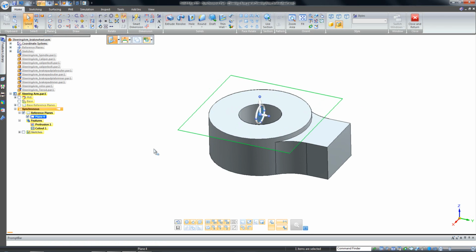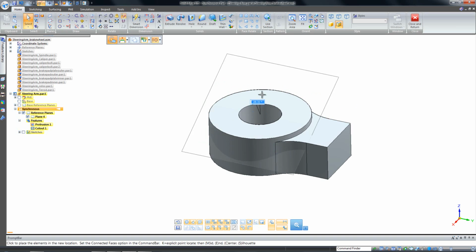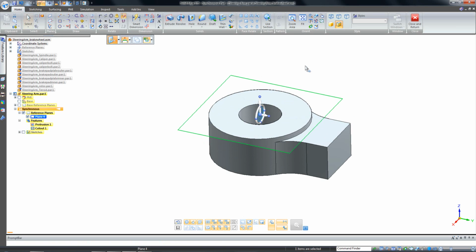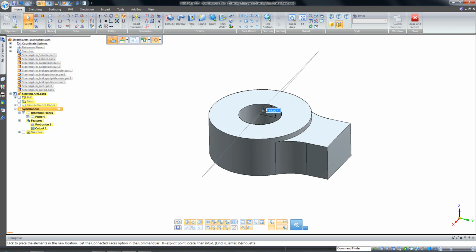work than is necessary. With Solid Edge, when you're working in synchronous, I can easily touch the face of the part and it creates a coincident plane, but notice how the steering wheel automatically pops up. So basically, if I wanted to create an angle, I can go ahead and do that, or if I wanted to change the angle or the way that the angle is being modified, I can also come through here very easily and change the orientation of the steering wheel and maybe create an angled plane in this orientation.